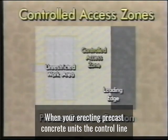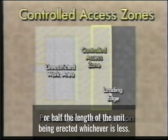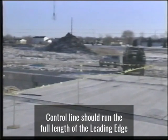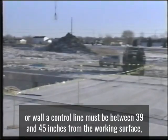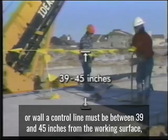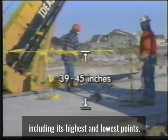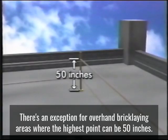When you're erecting precast concrete units, the control line must be at least 60 feet from the leading edge, or half the length of the unit being erected, whichever is less. The control line should run the full length of the leading edge and be connected on each side to a guardrail, post, or wall. A control line must be between 39 and 45 inches from the working surface, including its highest and lowest points. There's an exception for overhand bricklaying areas where the highest point can be 50 inches.